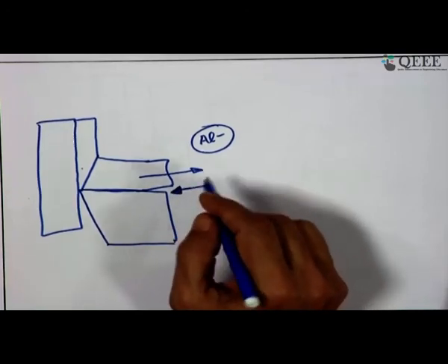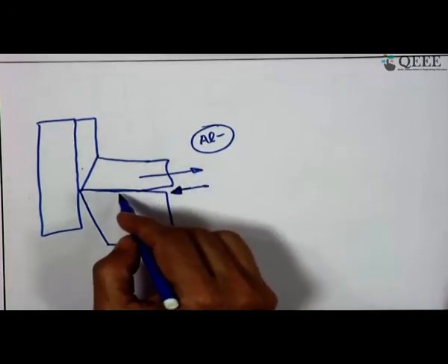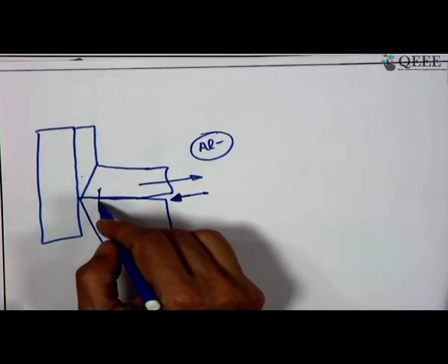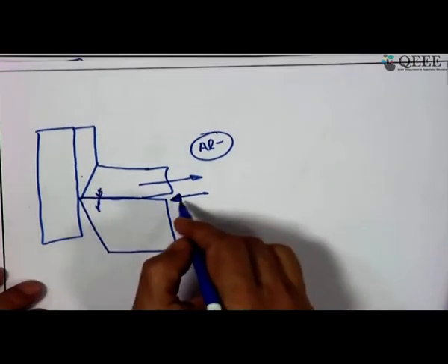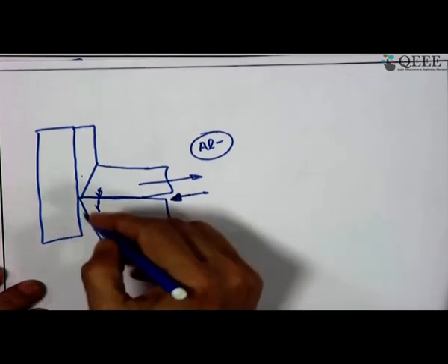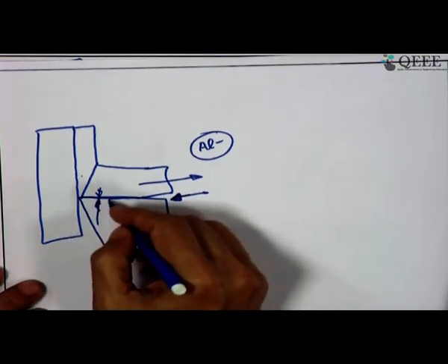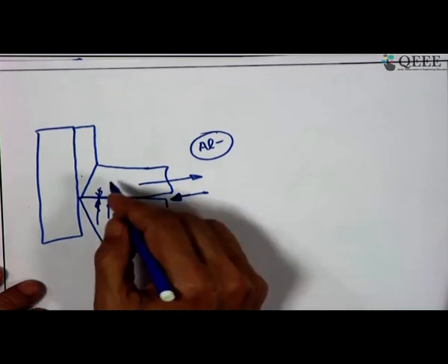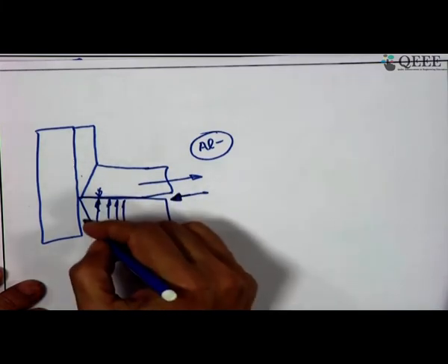There are now various techniques for the chip-tool interface, but just putting a nozzle from this side, the way we conventionally do, won't give you much benefit because it cannot penetrate, as the pressure there is quite high. So, the pressure should exceed that. There are ways to direct the nozzle, with some perforations, from this side or from this side.